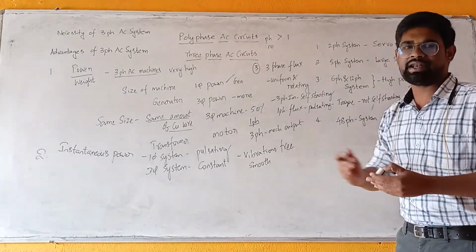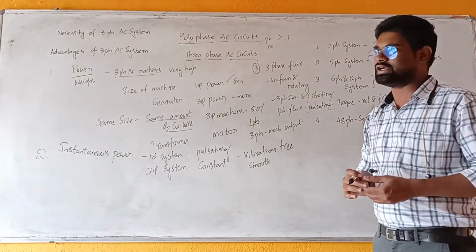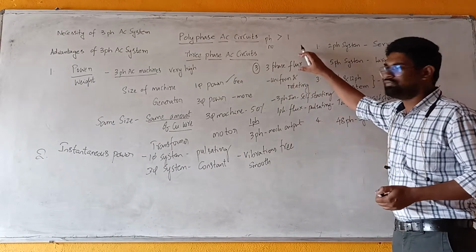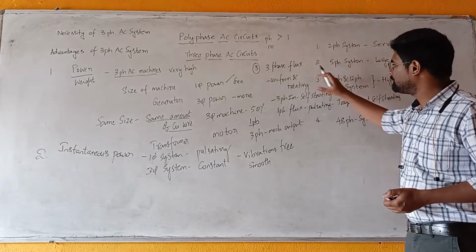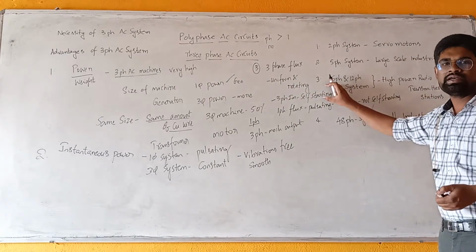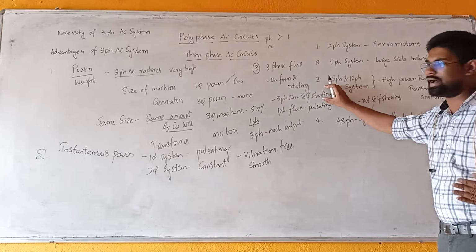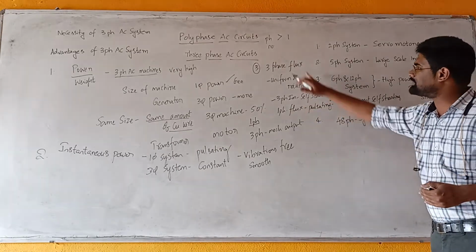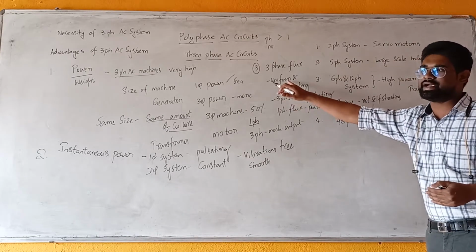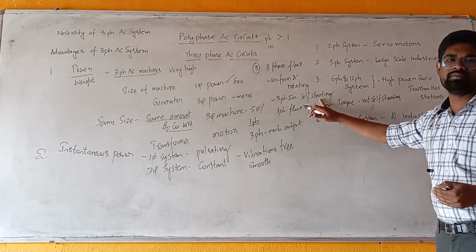If we make a comparison between three phase induction motors and single phase induction motors, because the flux produced from three phase supply is uniform and rotating, three phase induction motors are self-starting motors. No additional arrangements are required to make the motor self-starting. Naturally, the three phase flux is rotating and uniform, so three phase induction motors are self-starting motors.